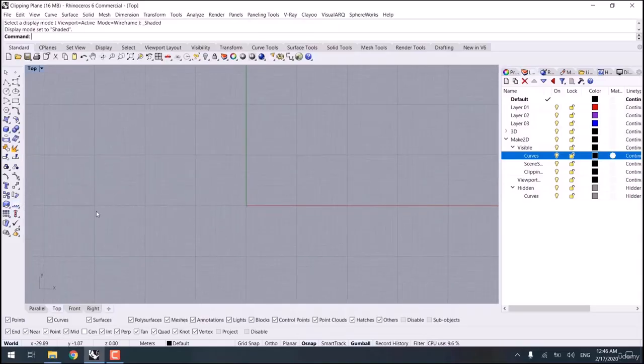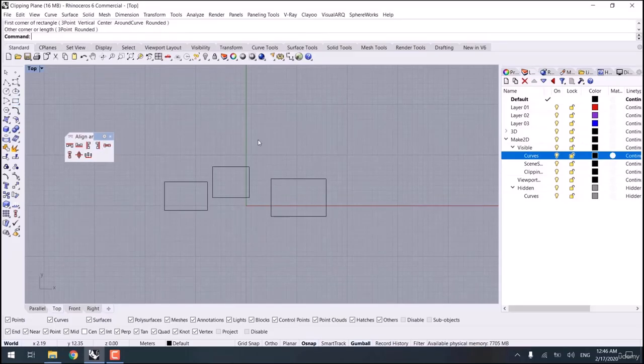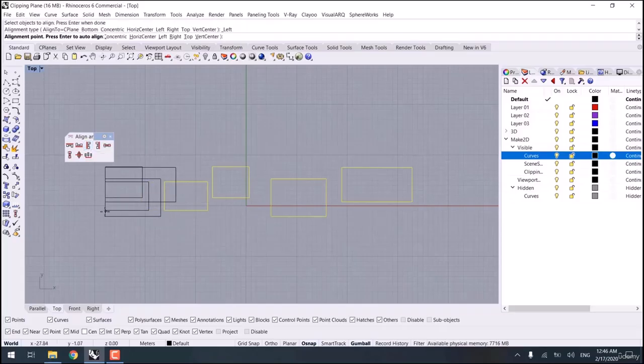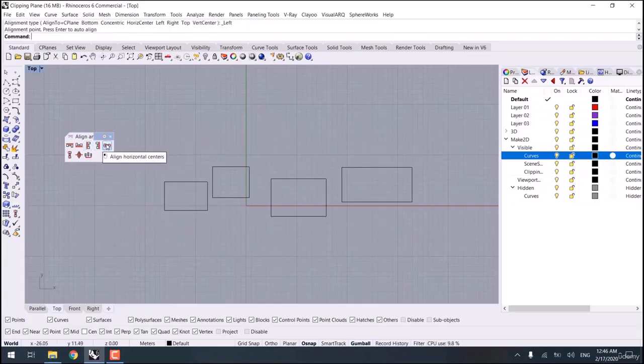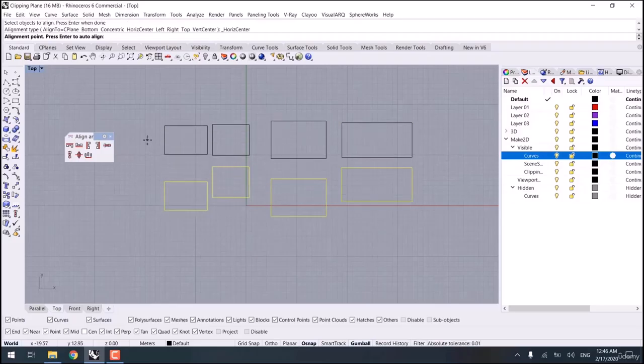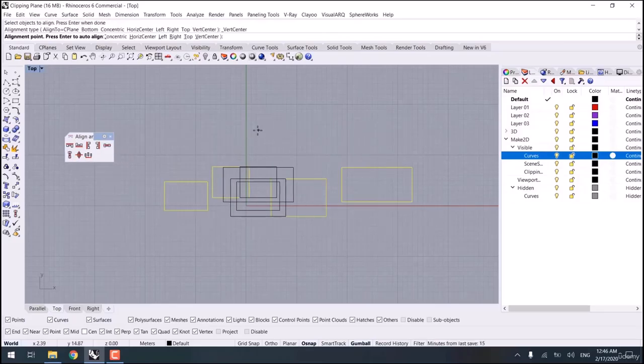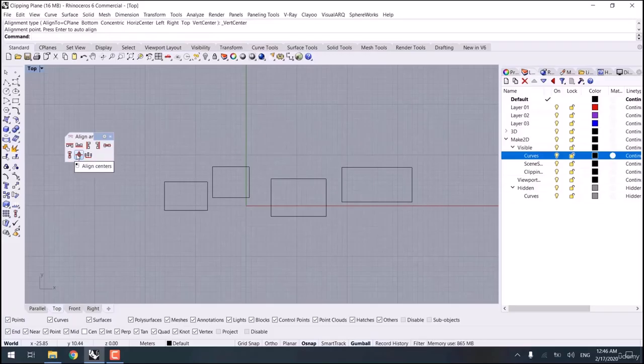And the next command that you're going to learn, or somehow we're going to have a brief review upon them, are the commands in the Align toolbar. As you're all probably familiar with align tools, you can align the specified objects with each other. For example, align top, or align bottom or down, align left, then we align them at the left side, and also align right. Check it out from the origin point, and also horizontal and vertical, and align centers.